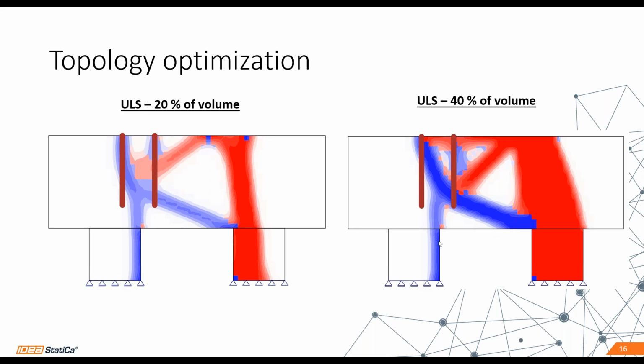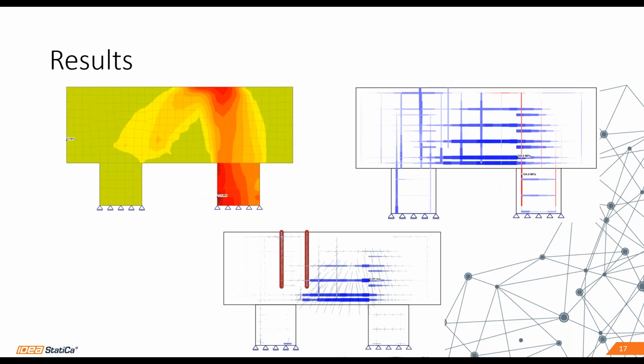So it will tell you that you can consider some tensile forces in the piles. So you should put some reinforcement, because from the assumptions the concrete in tension is neglected. And we will move on to the interpretation of the results, but I will leave it to the application.